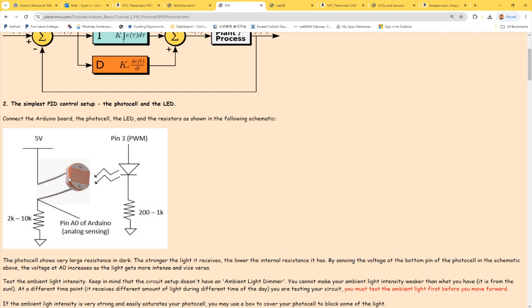Okay? So what you can do is set up a brightness level of the LED in your program. For example, I want that brightness to be a certain level, because this reading will be digitized. It's the same thing as the resistance and another resistor here, so it's a voltage divider. So you're reading a voltage here and it's digitized by the ADC, right? Make sense? That's light dependent. It's not temperature dependent right now. It's light dependent. So the resistance reflects the light intensity in the room. So you can digitize that voltage signal, okay? And you can set a set point.